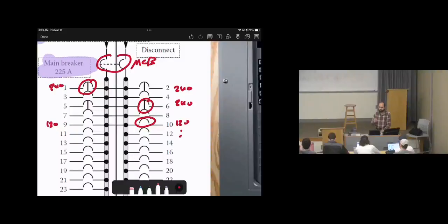So basically, whenever there is a double pole switch, this means live and live, then we will use the 2-pole switch, which is 240. If it's single, then this is 120. Again, when you go to your home, look at the panel, then you can say, okay, this is 120, this is 240. Okay, how can I know this is the main circuit breaker? It will be 3-pole, 3 things. The main circuit breaker is based on 3, while the others are 2, 2, 2, or 1, depending on the voltage level.